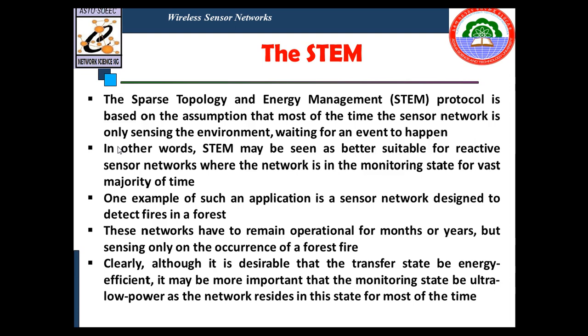The node that wants to communicate, that is the initiator sensor node, sends out a beacon with the ID of the node it is trying to wake up, that is the destination sensor node. This can be viewed as a procedure by which the initiator sensor node attempts to activate the link between itself and the target sensor node. As soon as the target sensor node receives this beacon, it responds back to the initiator node and both keep their radios on at this point. Whenever they need, they communicate with each other by periodically activating.